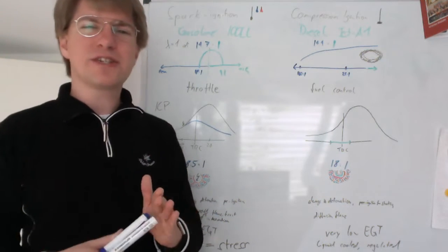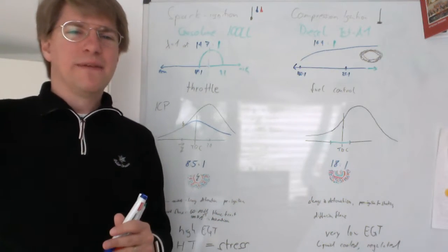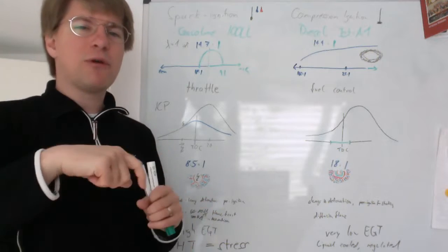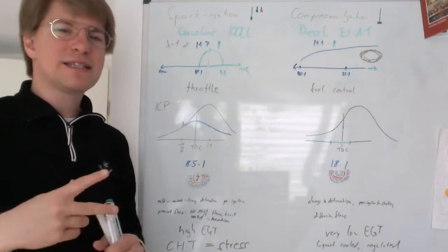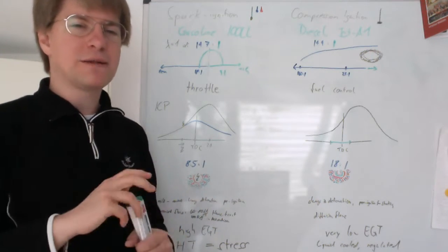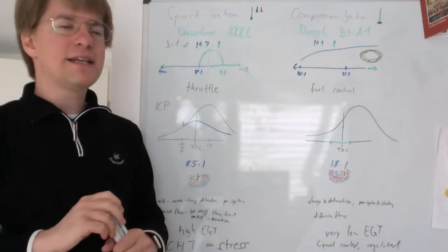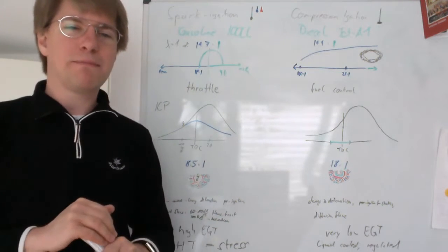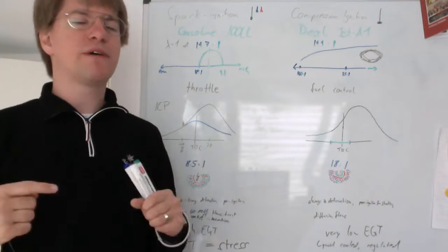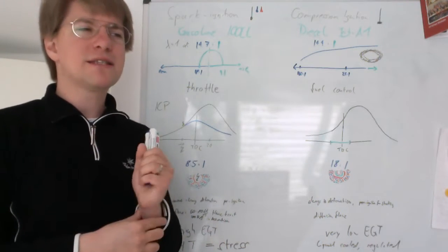So the propeller system is the same, it's just that the input that we give to the propeller governor, instead of having the blue knob operated by the pilot, in case of the Diamond diesel-powered airplanes, this input comes from the FADEC computer instead of the pilot.